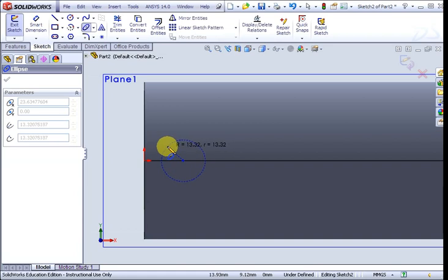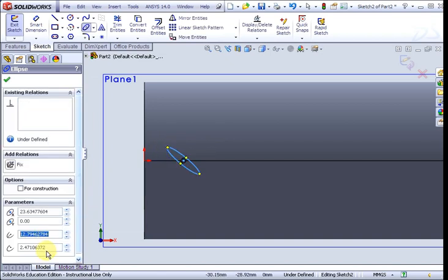So also you have to properly define the angle, and the geometry here will be just arbitrary. We can do here 2 mm thickness. Okay, it's a bit far. We can pull it back a little bit, 20 mm from the 0 point.